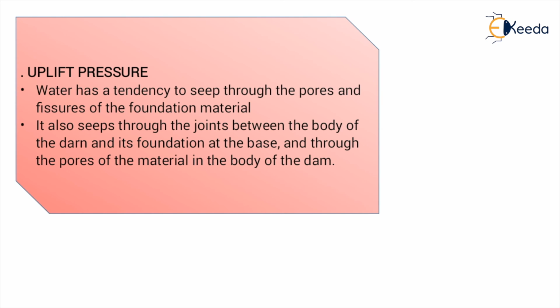According to this standard, there are two constituent elements in uplift pressure. The area factor, also called the percentage of area on which uplift acts, and the intensity factor, also called the ratio which the actual intensity of uplift pressure bears to the intensity gradient extending from head water to tail water at various points.